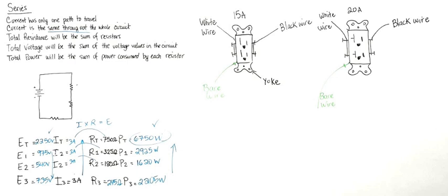But there are some instances, for example, when they would call us for a service call at 2 in the morning because a building lost power and we needed to go check it. Let's say somebody was connected to a machine, and the generator was going to be working, but only for a couple of hours, so we needed to work with live power. So we needed to take out our specialty gloves and boots and make sure we were safe and secure, because now we were working on live wires, right? As electricians, safety has to be first. Depending on the environment you're working in, you have to use the tools that are appropriate for the use.